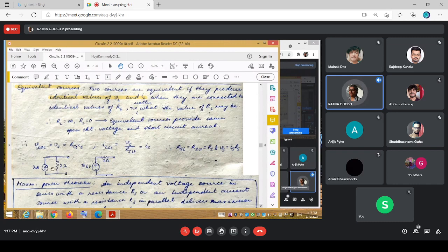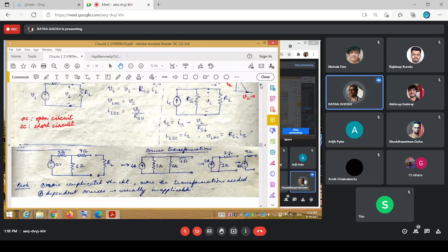Again, from the forward point of view, when you're analyzing a circuit, beyond this point, supposing you've got a parallel network, then instead of having just this one series branch, you can convert it into a parallel branch by an equivalent source transformation and have it in parallel with the rest. That allows you to analyze more easily, and that is exactly the principle of source transformations that we will talk of.